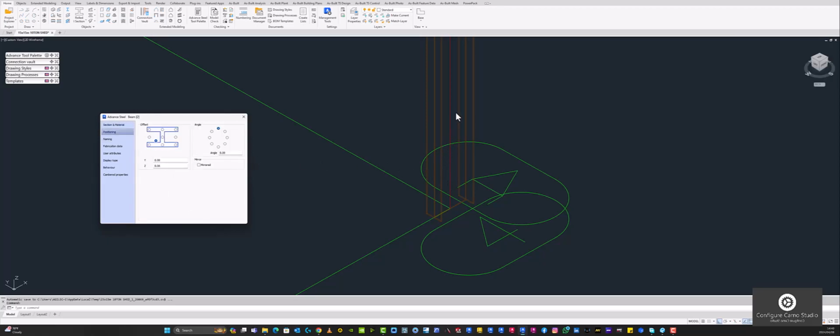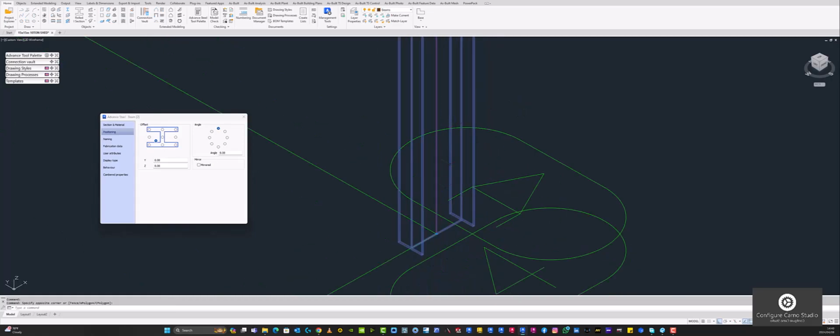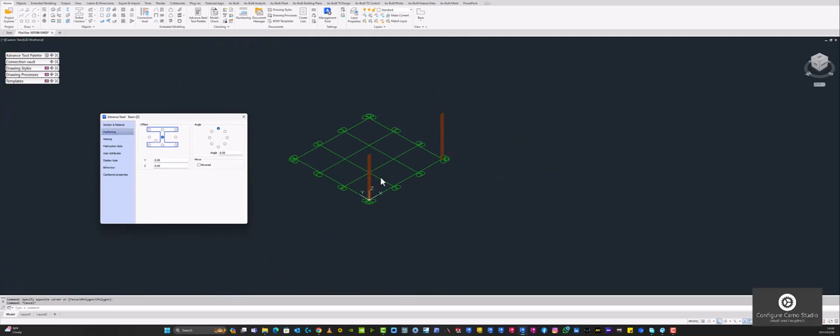Positioning now, you're positioning according to, if you see on your steel section, you've got this red line axis, this axis line, which is in red in color. It points out the insertion point where you inserted your beam or your column or your rafter. So from there, you choose the position that you want, whether you want it on the center of the flange, corner of the flange, wherever that you want to just pick according to the points. And then if you want to rotate it, you can rotate using these points there. So that's how you rotate them. And then from there, we go to naming.